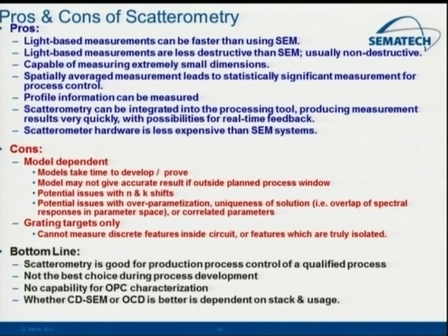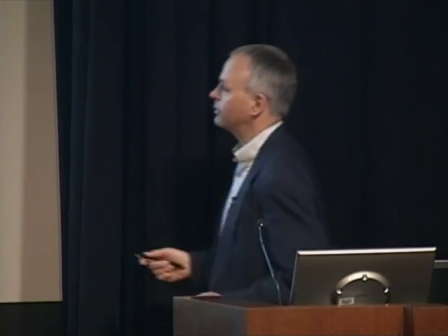You can extract profile information. Sometimes the tool is simple enough that you can put some of these basic ones attached to your etch tool or attached to your deposition tool and get real-time feedback information. So it doesn't even have to go from the etch tool to some other bay in your process line. You may be able to do it right on the tool itself. And they're also typically less expensive than SEM systems, although the vendors are doing their best to make these expensive as well, it seems these days.